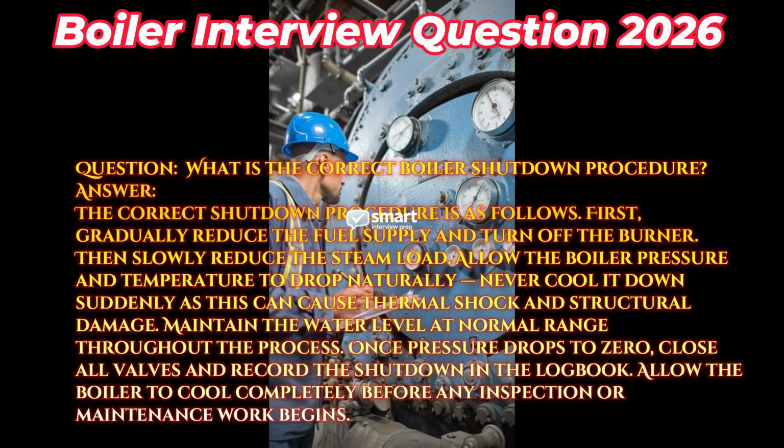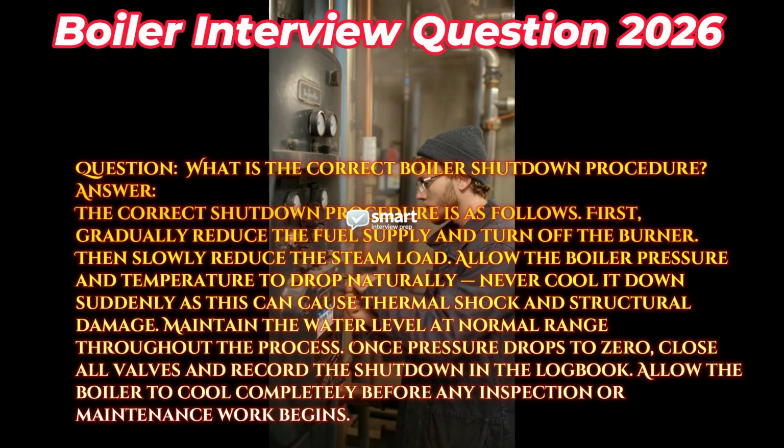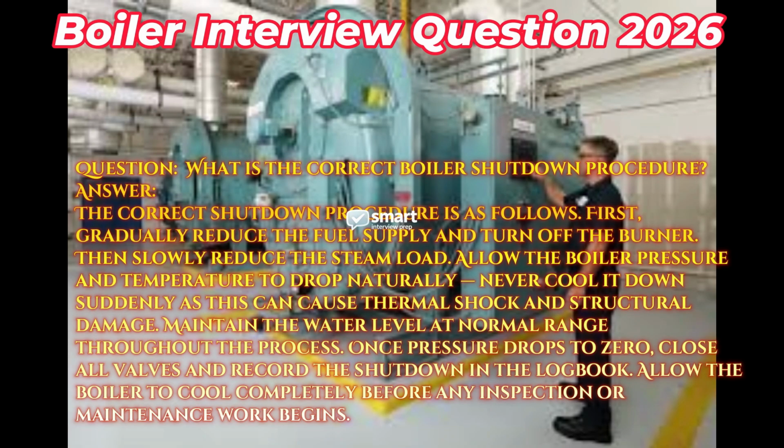Maintain the water level at normal range throughout the process. Once pressure drops to zero, close all valves and record the shutdown in the logbook. Allow the boiler to cool completely before any inspection or maintenance work begins.